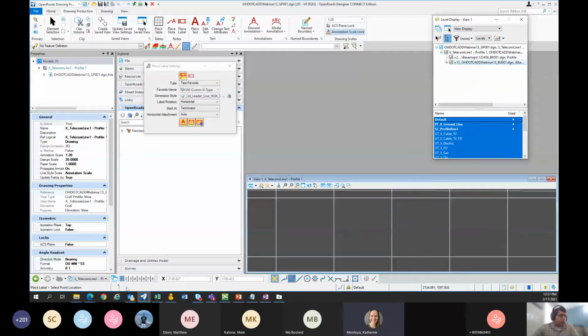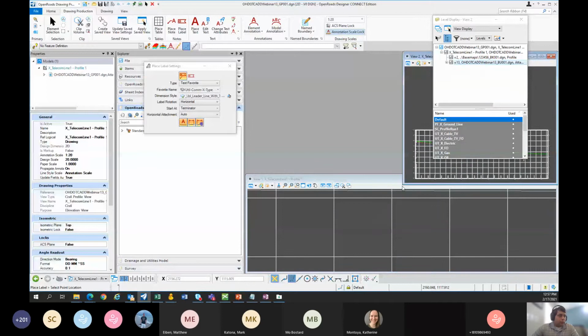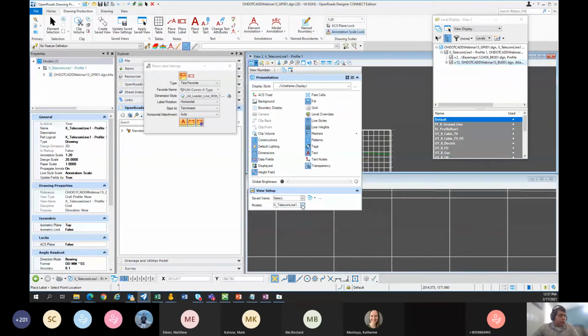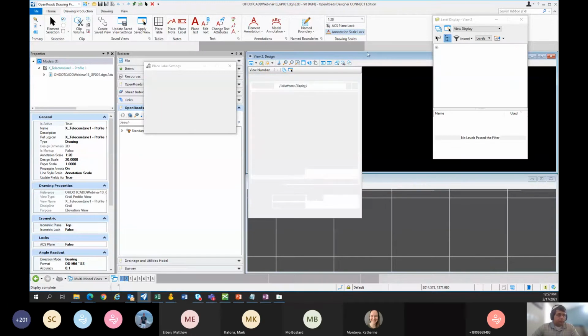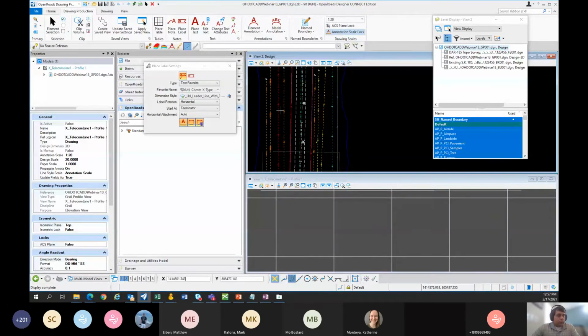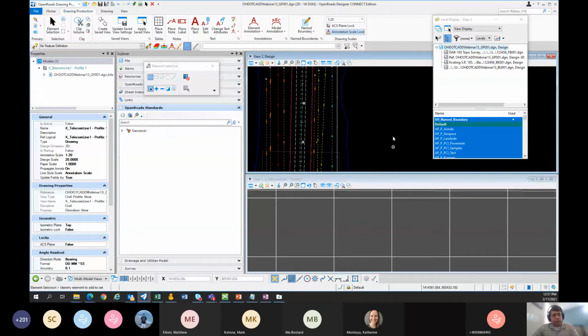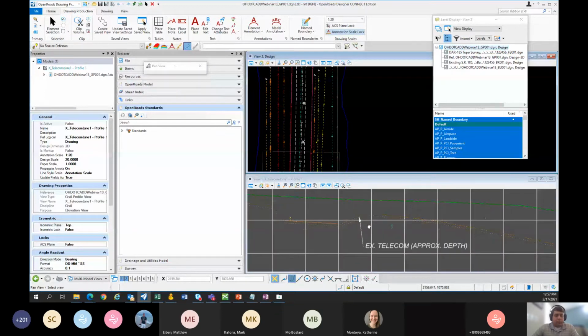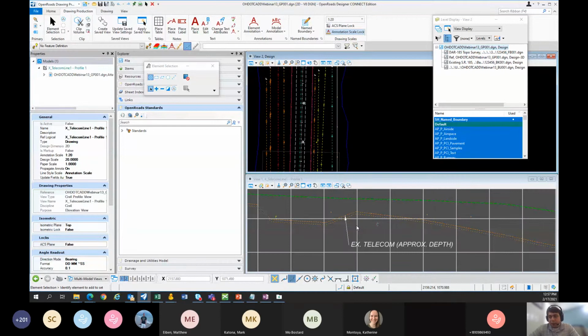I'm sure you guys have seen we talk about the problems with annotation across a reference, right? So if not, right now I am in ORD 2020 release 3. So the latest one. So if that's the case, I can somewhat get the annotation to work across the reference, but I'll show you the shortcomings. If I'm in anything before the latest one, annotation across reference is really not going to work.